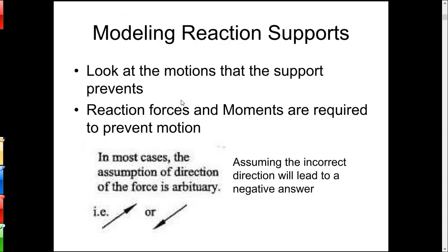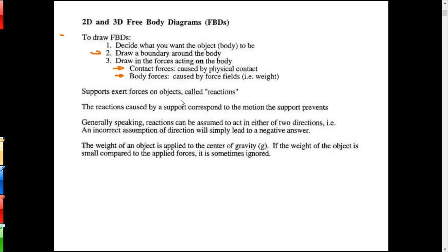All right, now what you do when you're working through these is you start with the applied forces, what's put on the object. Then you have supports on the object, different types of supports, and they will also exert forces on the objects called reactions. Okay, so I think of the applied forces as being actions. At the supports, you have reactions. Reactions are caused by the motion that the support prevents. So if a support prevents motion in the horizontal plane, it does that by applying forces in the horizontal plane.